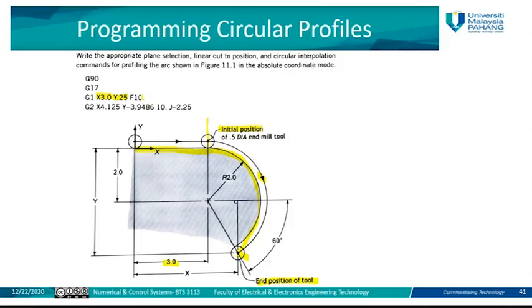And the feed rate is equal to 10. That means this is to define the movement from this point. If this is the 0 point and the diameter of this circle is 0.5, so the radius is 0.25. That means this center here will be at 0.25 of y. So it will move to this point, which is 0.25.